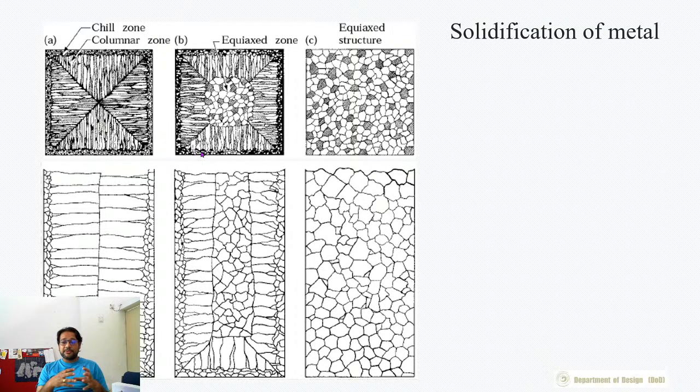Okay, because what happens is that the molten material, imagine even in a microscopic view, the crystals, since the molten material takes a bit of extra time to cool down, the crystals have a chance to grow a little larger, right? So because of which the grains themselves become slightly larger. So here the grains are slightly larger than case 1, case A, but they still form a smaller grain structure compared to other internal grains that will be formed in this, and it forms an internal layer of insulation for the material.